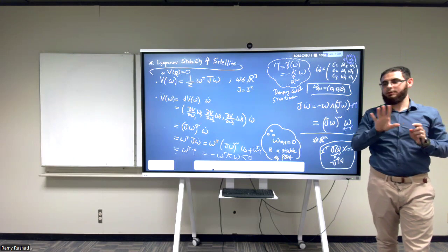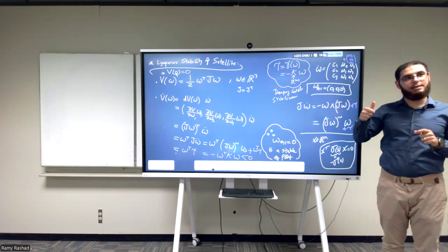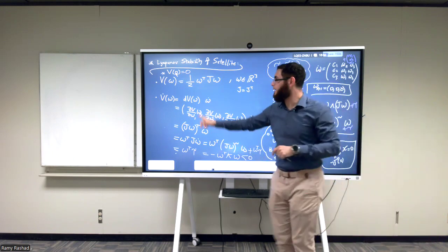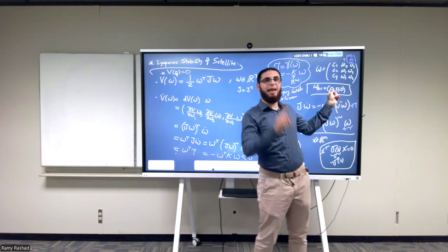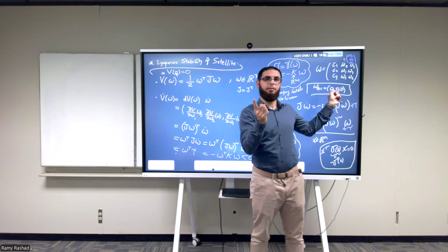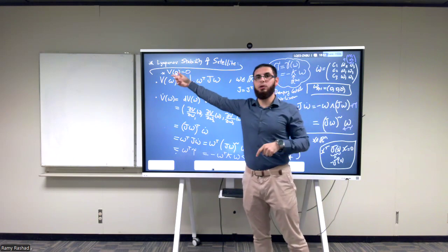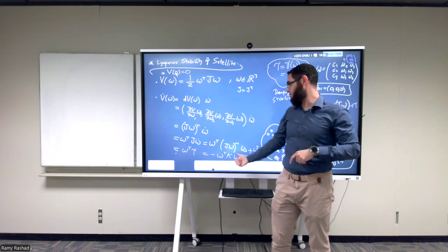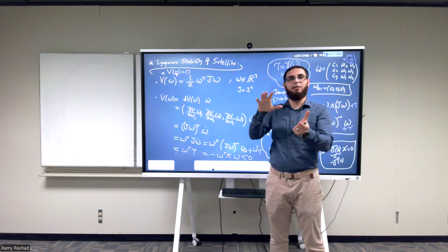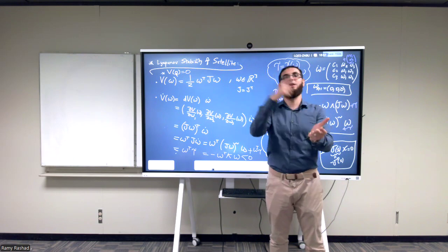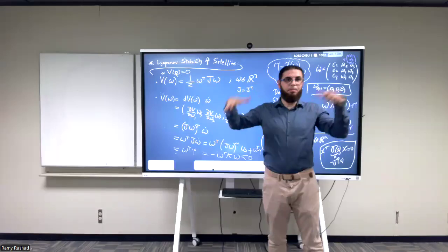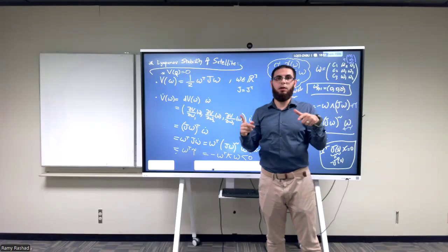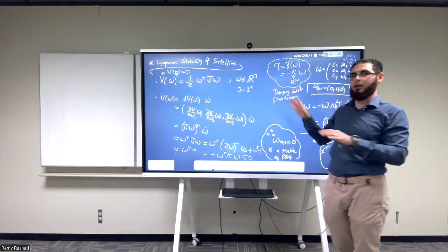If you find another Lyapunov function that has a minimum around the equilibrium point that is rotating, and you show that its corresponding V dot along the trajectory of the system is negative definite, it means that the trajectories of the system will converge to this spinning case. And it means that I'm going to damp the other directions and only rotate in one of them.